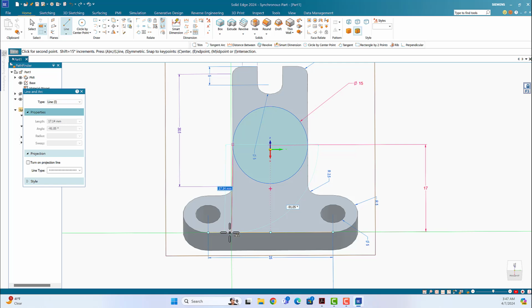Is it vertical? No. I can put it like this. I need the dimension to be 17, enter. And the angle should be, okay, 9. Okay, that's good. I'm going to click because the angle is 9. So I created this one. Right click to get out.